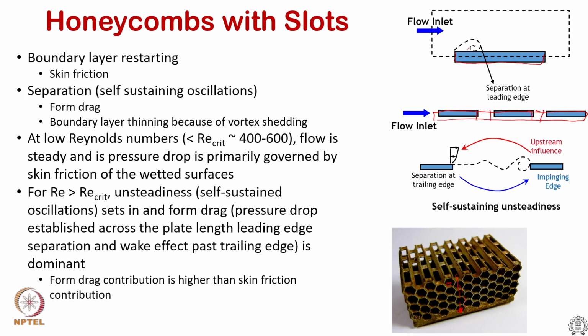So, the flow enters, there is some kind of separation here, and as it exits, there is an impingement zone depending on the spacing between these fins. It will start to influence the upstream flow itself because of separation, and the boundary layer that is developing will be affected by this, and it creates an unsteady effect. And so the goal of many of these unsteady flow or laminar flow instability based heat sinks is that they want to achieve as low a Reynolds number as feasible to achieve the flow unsteadiness.